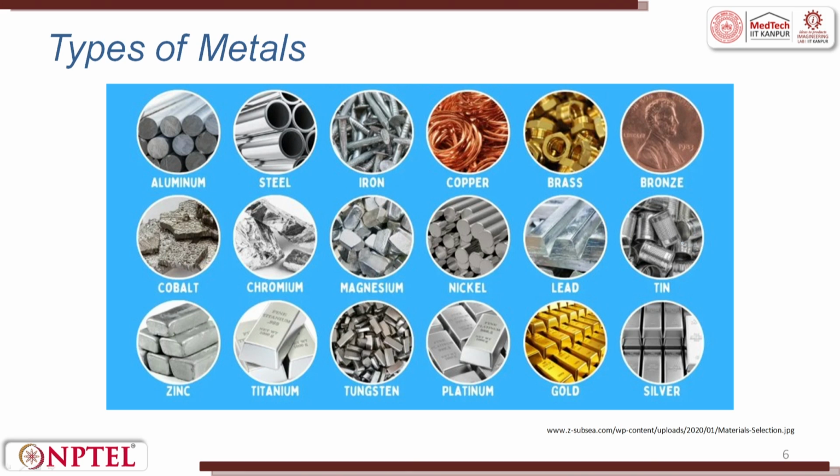When we talk about metals, there is a spectrum of materials which are available. No pure metal is good for engineering application. We always look for an alloy, because in a pure metal you will have no defects. If there are no defects, then it becomes very difficult for you to deform. So, we always try to use an alloyed material. What is the alloying? It is left to your choice depending upon the service condition, and then the percentage is chosen. Then it is mixed to get the required strength or to meet your requirements.